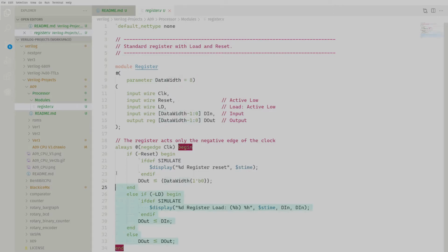So here is the main portion. This is a behavioral block. It's an always statement, and it is sensitive to the negative edge of the clock. In our processor, we will do two things. It's like a tick-tock. The rising edge of the clock will be to configure things, and the negative edge of the clock will be to do things. It's the action portion of our cycle,